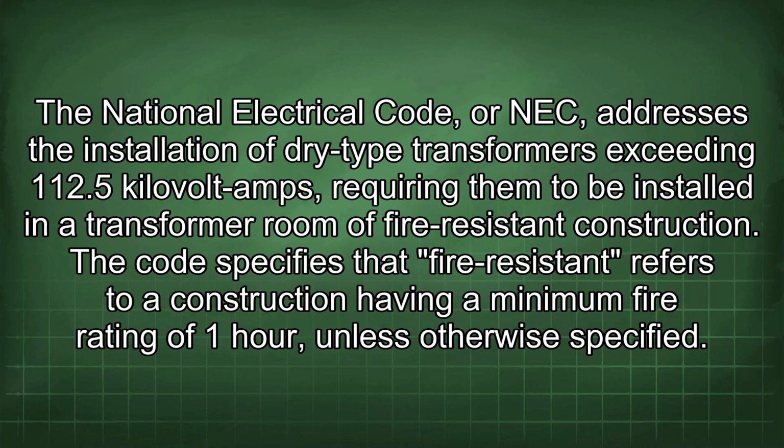The National Electrical Code, or NEC, addresses the installation of dry-type transformers exceeding 112.5 kilovolt-amps, requiring them to be installed in a transformer room of fire-resistant construction. The code specifies that fire-resistant refers to a construction having a minimum fire rating of 1 hour unless otherwise specified.